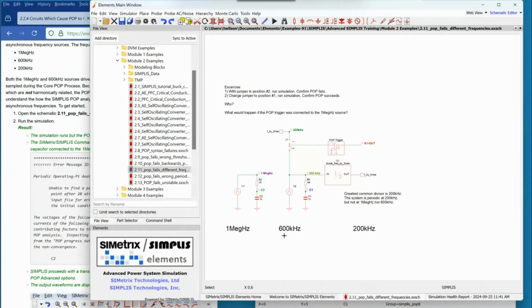Also, if you have a design that's basically a battery charger, and you don't design the battery model correctly, and the battery voltage is slowly charging during POP, it looks like a gigantic capacitor, so effectively POP will never succeed that way. Yes.